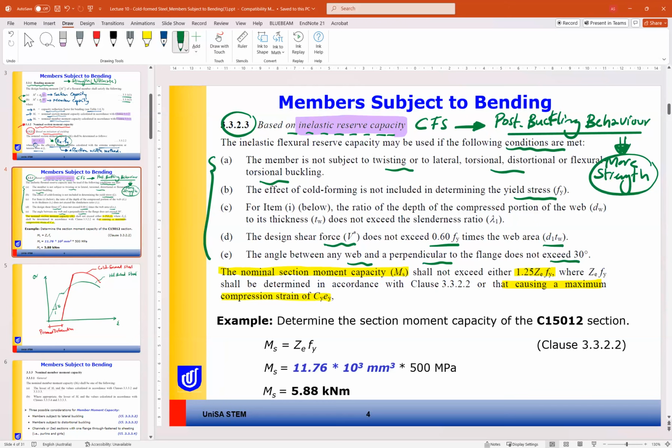So MS cannot exceed, or should be less than or equal to, 1.25 Z effective F yield. What does this mean? The maximum increase in our section capacity over the normal yield calculation is only 25% more. So the inelastic reserve capacity is limited to 1.25 times the value from the elastic capacity. Okay, a quick example here about the calculation.